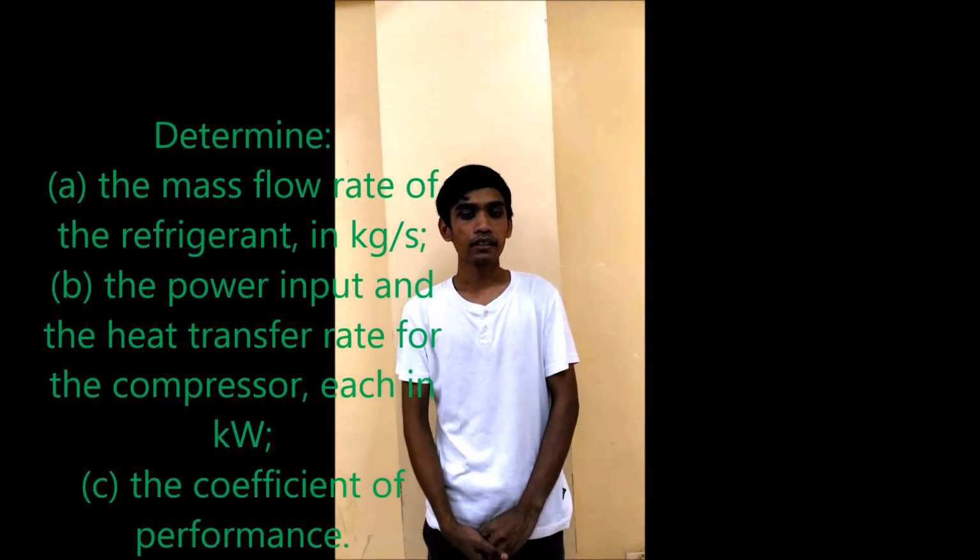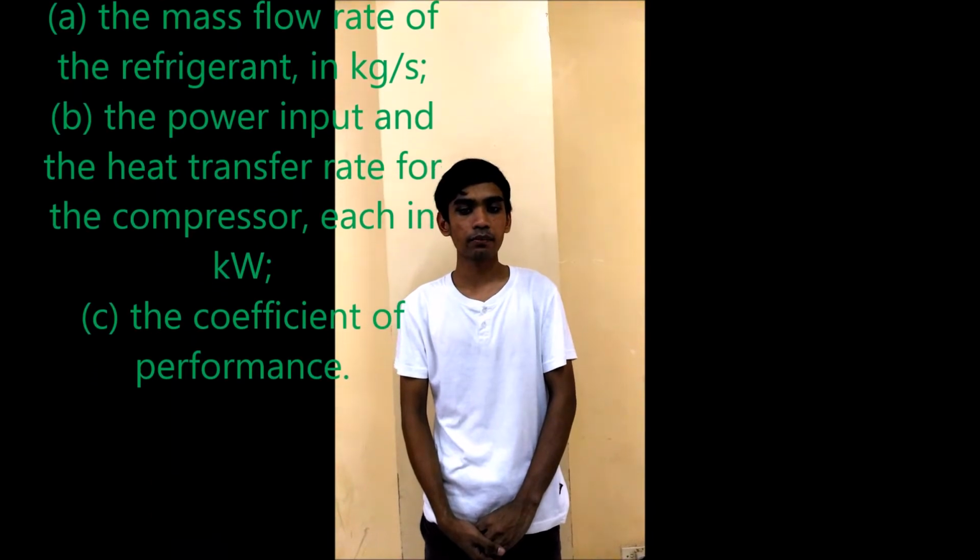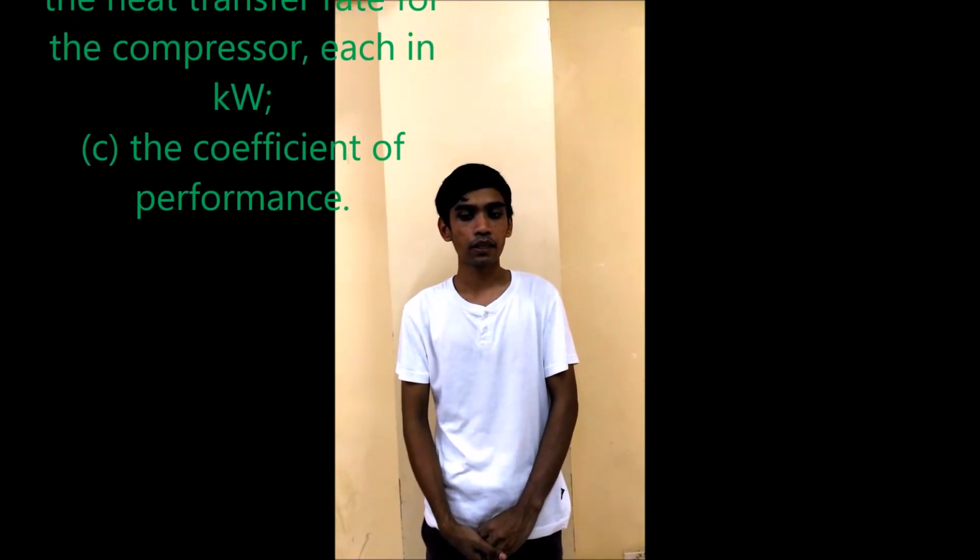The condenser is water-cooled, with water entering at 20 degrees Celsius and leaving at 30 degrees Celsius with a negligible change in pressure. Heat transfer from the outside of the condenser can be neglected. Determine A, the mass flow rate of the refrigerant in kilograms per second. B, the power input and the heat transfer rate of the compressor, each in kilowatts. And C, the coefficient of performance.